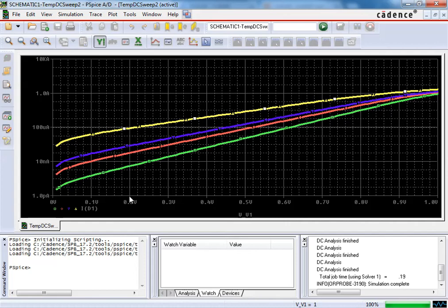And what do I mean here? Well, at 0.2 volts, we've got just below 10 nanoamps. But then, this is at -40, this would be at 125, and you've got 100 microamps. So 100 microamps and 10 nanoamps, that's a huge difference as far as magnitude of current. 100 microamps you might still think is a small current. It is. But if you're thinking about this not being turned on yet, that's a huge amount of, quote, leakage current, which would create even more heat. So it could cause an issue. So you have to see how these things vary with temperature.